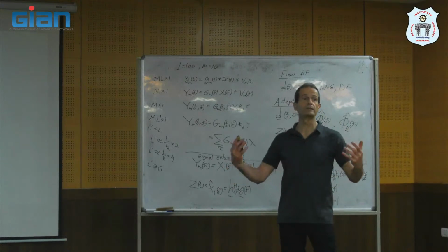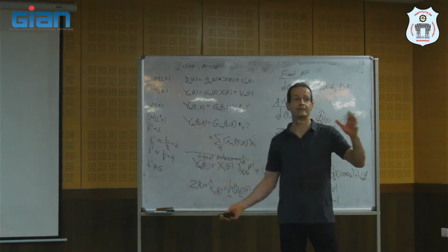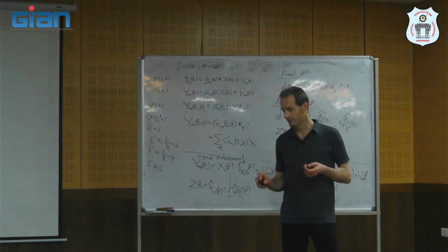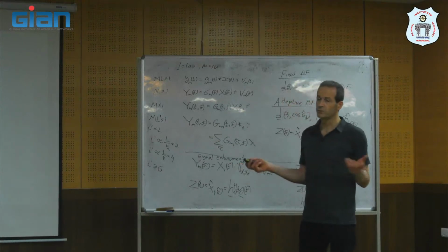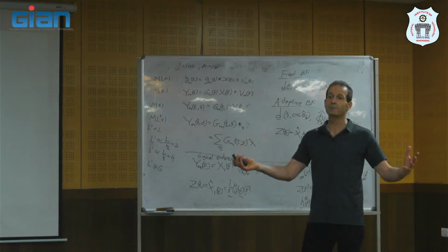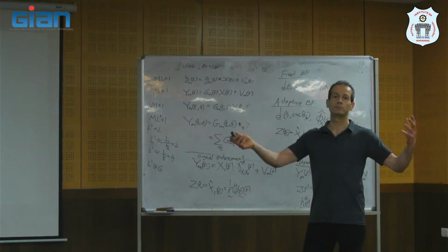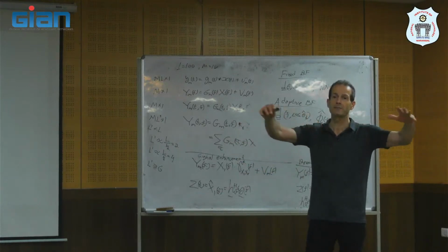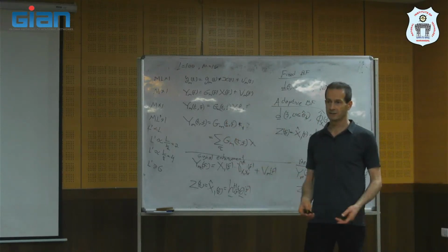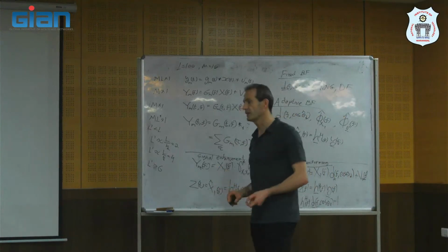Or we try to suppress noise that comes from an unknown direction. Also, something like that. Okay? So sometimes if we don't know the direction, we assume that all directions are equally probable. So all directions of the noise are equally probable, so we try to reduce them, like if there is noise from all directions, because we don't know. So this is the directivity factor.